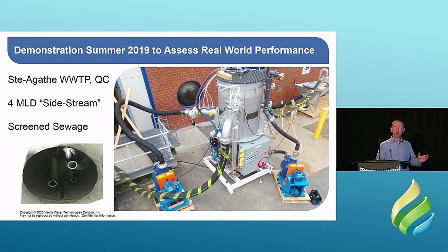So the pump on the left is extracting water downstream of the screens. So we're taking screened effluent, pumping that into the grit system. You can see that coming up. Not sure how clear it is. I'm not sure I can really point to things in this setup, but there's a manifold on the left, that black pipe is coming into the grit chamber. That's the influent manifold. You can see a bunch of little tubes going into there.